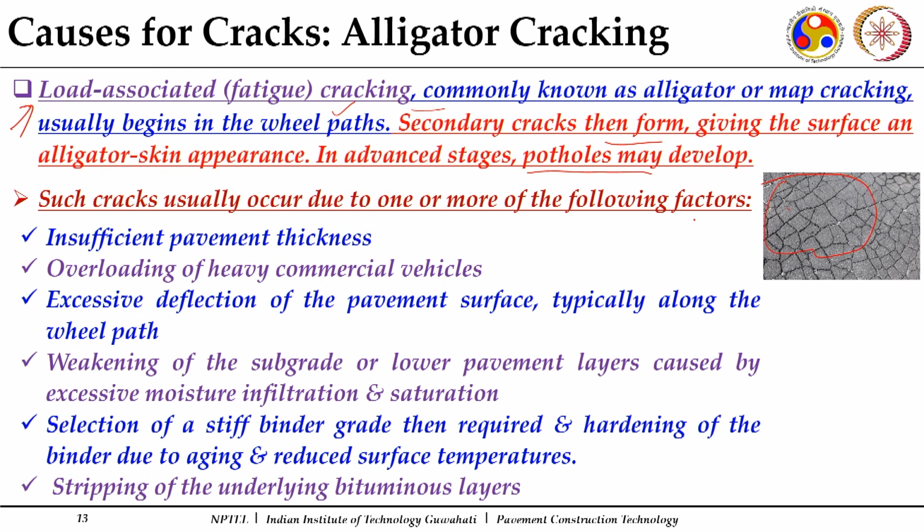So, what may be the possible causes for alligator cracking? One is insufficient pavement thickness. So, more deflection will happen, the material will deflect to a higher level, and this will induce tensile stresses which will be more than the strength of the material, and cracks get initiated.